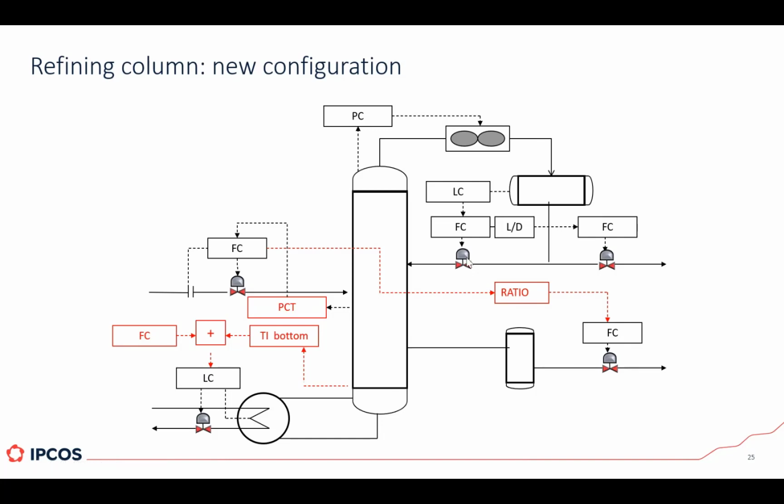So what do you need to do? In that case, you need to find a pressure compensation for your temperature measurement. And that's exactly what was done. Because the mixture that is being separated here is, let's say, somehow an easy mixture to find literature about, it was possible to find enough literature to calculate this pressure compensated temperature, and it matches the real behavior very well.